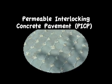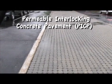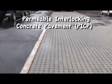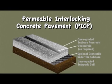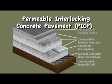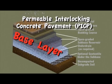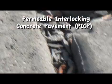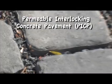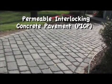These pavers tend to be more costly than freestanding pavers, but their durability and aesthetic design have made PICP the most popular type of permeable paver system. The construction methodology is similar to that of freestanding pavers. Since these pavers are generally intended to support vehicles, the base layer is critical. Rather than sand, PICP generally uses 1/8 inch diameter stone to fill the spaces between the pavers. Additionally, because interlocking pavers are more difficult to install than freestanding pavers, an experienced contractor is recommended.